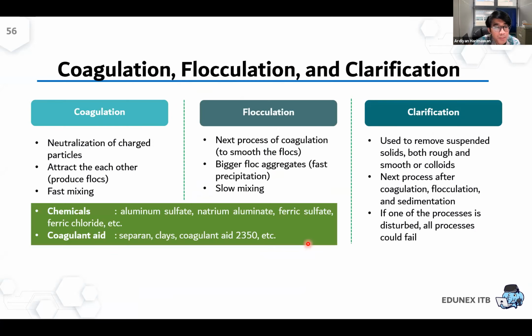So basically, this one that will happen. Coagulation is the process of neutralization of charged particles. So why is it always suspended? Because it has charge on the surface. And because each particle has charge, they will continue to be suspended in the water. So we can add some coagulant, and then we do the fast mixing.